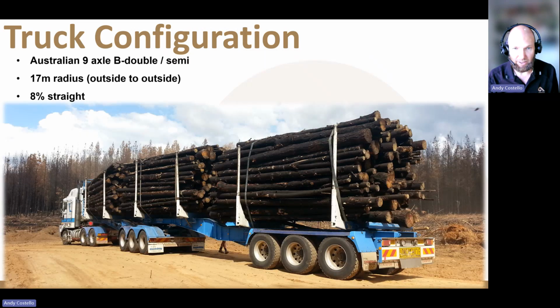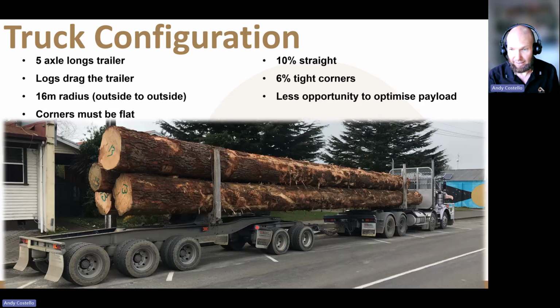So just to run through them really quickly at a high level, from worst to best, an Aussie B double. It's got no extra traction up the front, but it's got 6 axles behind it and a whole lot of weight. Being a couple of semi-trailers, it's also connected high on the truck, which, as the truck's going uphill round a corner, gives the trailers more leverage to try and take the weight off the outside drive tire. If it goes light, it loses traction. So that doesn't help.